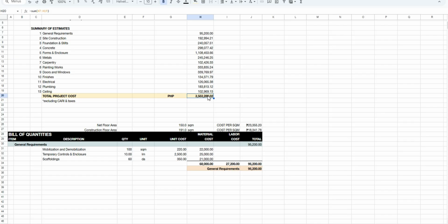If you want to have an agreement with the client that if we go over 3.5, I will pay the excess, it's called maximum guaranteed cost. But many people don't do that because it's very risky, except contractors. That's why there are also performance bonds, insurance bonds, and retentions. Retentions meaning costing that will not be released by the client until the work is done and fully fulfilled according to the specs, plans, and turnover with quality.